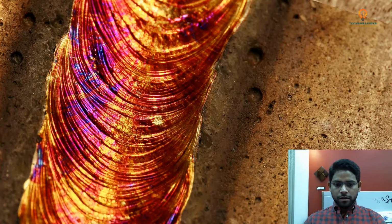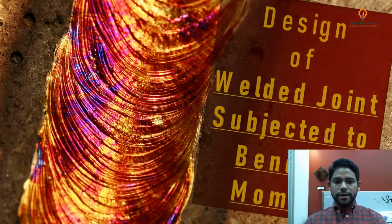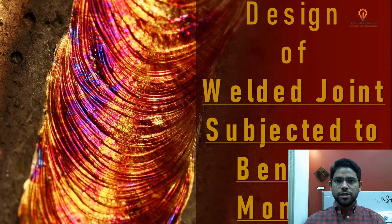In this particular case, this plate is the plane of your weld, whereas the load is applied at this point. So the difference is that in this case the load is out of the plane of the weld, whereas in the previous case the eccentric load was an in-plane load. Since we have established the differences and the similarities with the previous case, let's start with the design of a welded joint subjected to a bending moment.